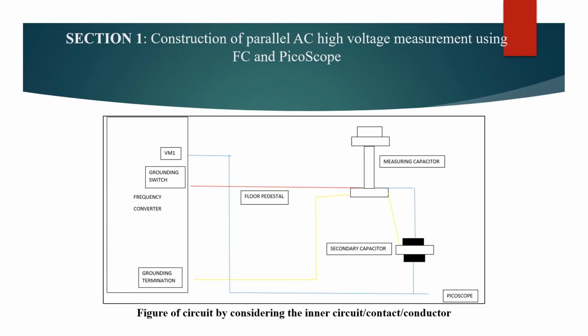Select the channel that has been connected to the Picoscope and make sure the channel is activated. When the channel is activated, select AC for the coupling. Select the range that we need to measure for peak to peak. Then insert the divider ratio as the secondary unit voltage per division, and make sure the offset is at 0. At the data log, we need to select channel A and select AC because we want to measure AC. Last step, after completing the steps, we hit the reset button to reset the system that we have organized.